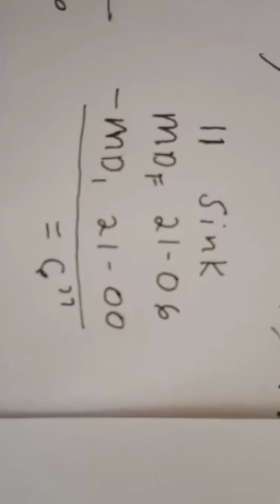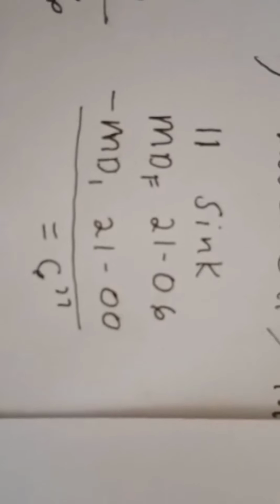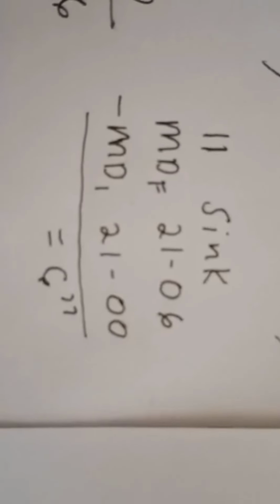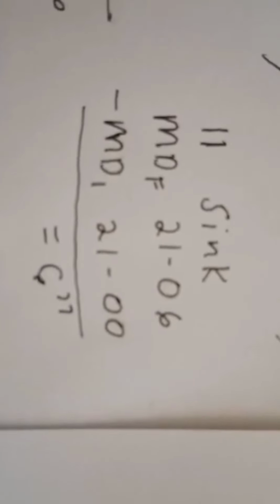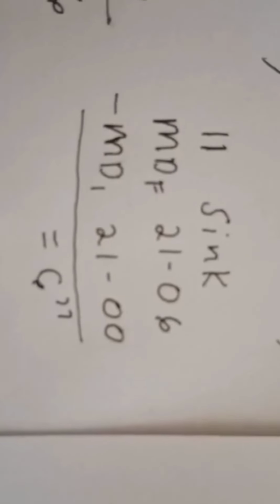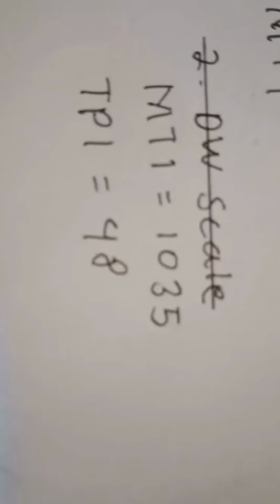Add enough weight to this vessel to sink it 6 inches. Once we've sunk it 6 inches, then we'll slide the weight back. By doing that, we're going to increase the forward draft by 6 inches. But wait a minute. So now we'll go on to step 4. This is where we have to calculate the trim change, or the total change in trim.